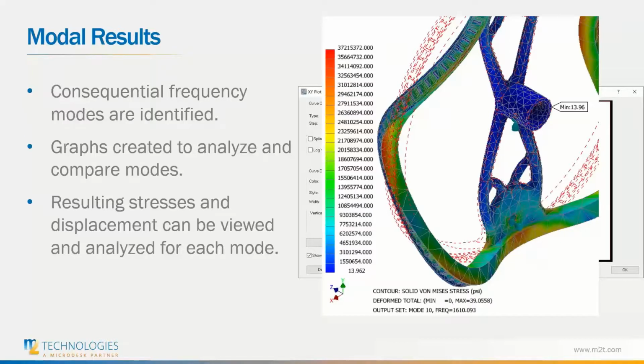1600 hertz. This provides us with an estimate of the stresses that will be on this part, and we can then either modify the geometry if we are worried about this frequency being a problem, or we know to avoid motors or other objects that are likely to cause this frequency within the part.